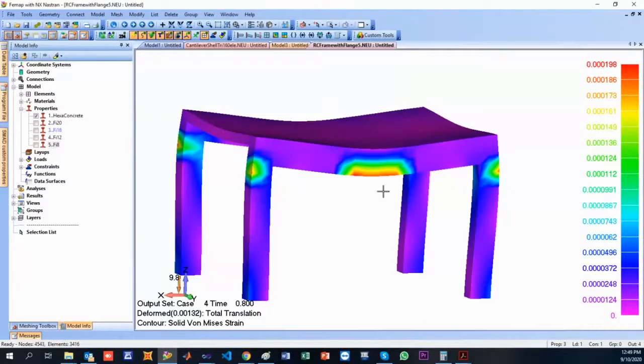Absolutely correct. So, due to the fact that we have a sort of bending about the diagonal axis of the section of this column, we have the development of a crack here. But so far, our professors told us that we have a rectangular section and bending moment, tension is at the bottom and compression is at the top. Now, this is the behavior of a real structure. We don't have a bending moment which is exactly symmetric and applied at the neutral axis that is parallel to the actual lower and upper fiber of my section. This is a myth. This is a simplification. So now you can start understanding what's going on within a real structure and how a real structure will behave.